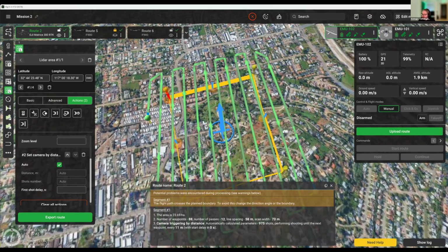Okay, another question. This is about the Astro drone, the Freefly Astro. You're saying that when you use the figure eight with the Astro, the drone will stutter at the waypoints rather than flying smoothly. We have encountered this specifically with some Astros; they do stutter at waypoints. It's simply due to the drone's behavior, so this will change based on what drone you're using. I know for some PX4 drones that's an issue. Autopilot-based drones tend to fly the figure pattern better, without stopping.